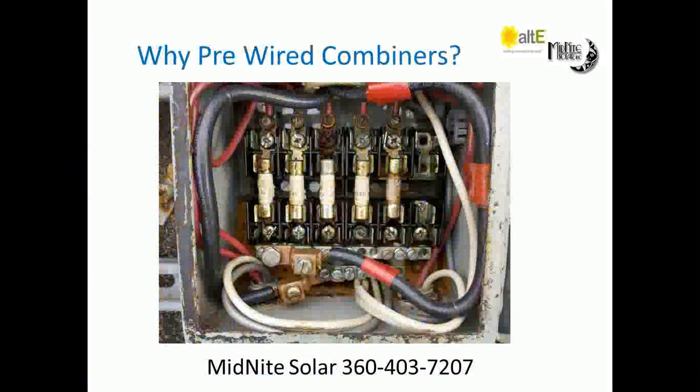So it's a little more elegant, and that comes back to that powering a village idea, because if you're doing AC coupled as a mainstay off-grid, you need 3-stage charging to properly charge the batteries. Otherwise, you're going to destroy the batteries in a short period of time. If it's an emergency backup, again, forget about the batteries. We don't care about the batteries because under normal conditions, they're being pampered like crazy by the grid. So when the grid goes down that 1 or 2 times a year, we're going to go ahead and use the daylights out of them and not worry about it.